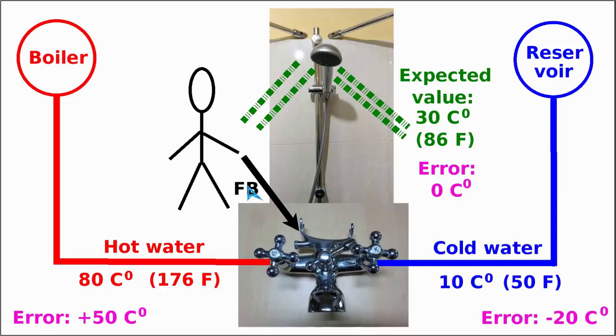And now the question is, what kind of feedback will it provide to our control element? In this particular scenario, for us it is clear that the right decision the controller should take is to then start closing very quickly the hot water valve.